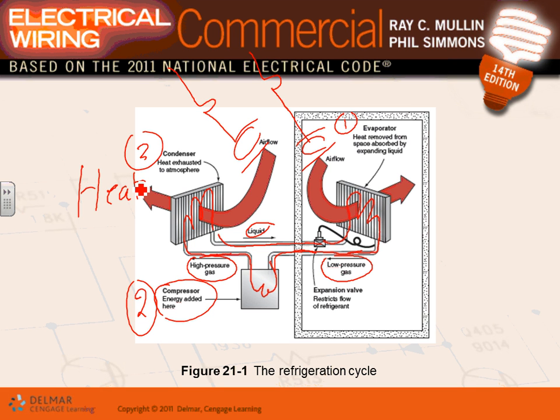So the last part is the expansion valve here. The expansion valve right here is just to regulate how much of this liquid is going to enter the evaporator, to control the process. Any comments, guys? Any questions about these four parts? We have the evaporator, which needs a fan. The condenser needs a fan, and the compressor, guys, my compressor here also needs power.